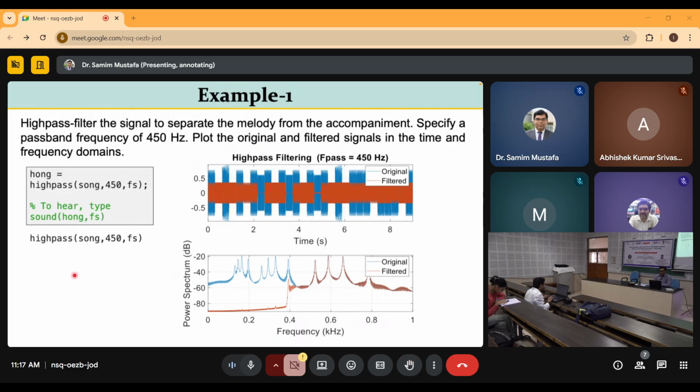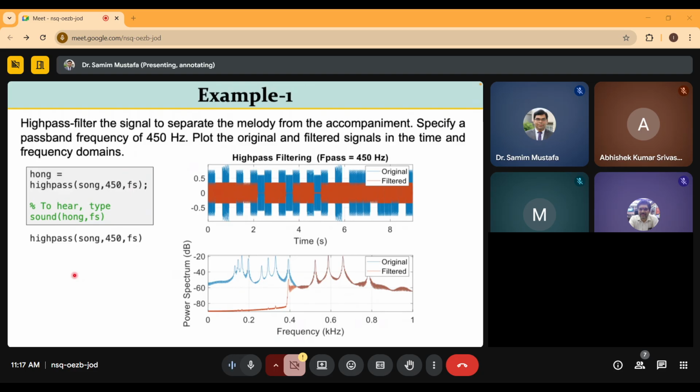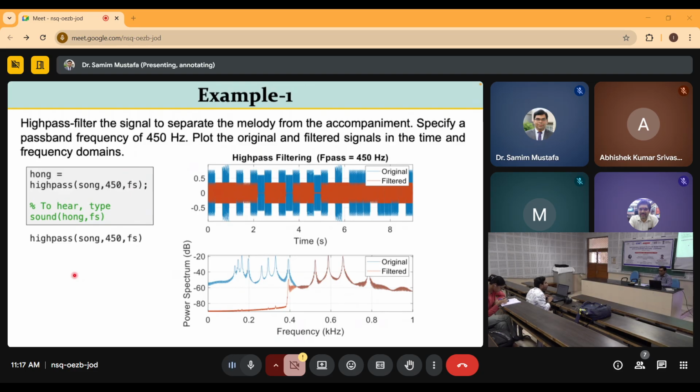So how is this relevant to you? Suppose, as I said, I have to eliminate the dynamic component from the static component. Dynamic component means it is due to the natural vibration of the bridge. The bridge is vibrating, that's why the dynamic response is produced. Or as a whole, the bridge and vehicle are vibrating. So suppose the fundamental frequency of the bridge is 3 Hertz or 4 Hertz, whatever it is, based on the length, geometry and other specifications of the bridge.